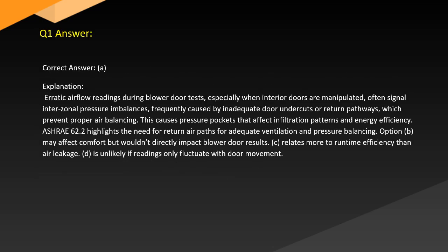Answer. Correct answer: A. Explanation. Erratic airflow readings during blower door tests, especially when interior doors are manipulated, often signal interzonal pressure imbalances, frequently caused by inadequate door undercuts or return pathways, which prevent proper air balancing.